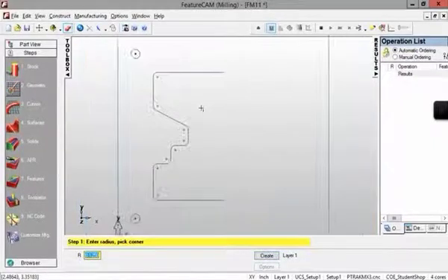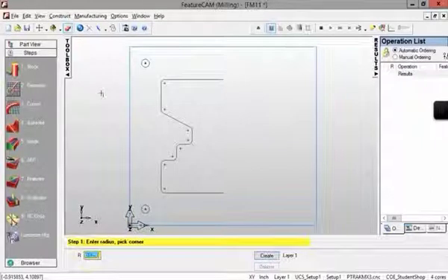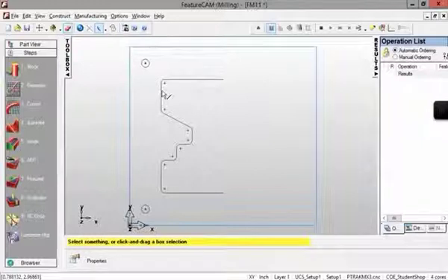So I think we have finished the left part, and the next step is going to be a reflection. First you want to cancel the fillet drawing mode by pushing the ESC button. Then you want to select all the lines and all the joins on your current design. You can use two different ways. One is just push Control plus A on your keyboard, and you can see all the lines and all the circles are in red color now. The other way to select them is to left click somewhere and drag a box.